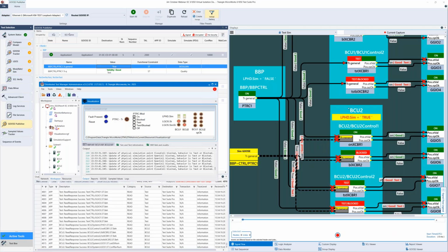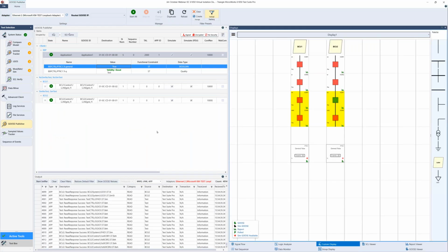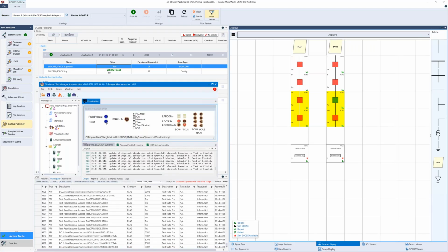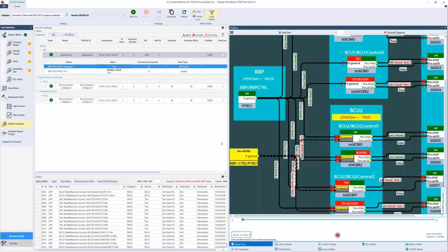What should happen is those still don't open, because remember, as Jackson mentioned, there is a latch. So once we have been in simulated mode, we will not go back and listen to the other ones until somebody tells us that we are not listening to simulated mode anymore. So if I now create a fault from this device, the VCU2 will still not operate. Before we do that, we need to do a reset so that everything is reset. And now we can do a fault from here, and we see VCU1 operates, but VCU2 did not operate because VCU2 is still expecting the simulated message.